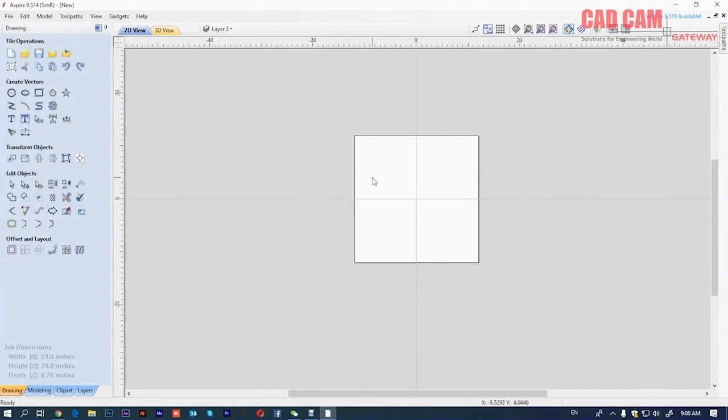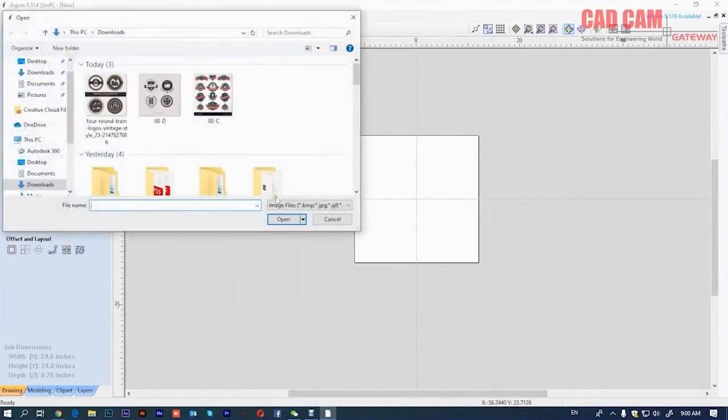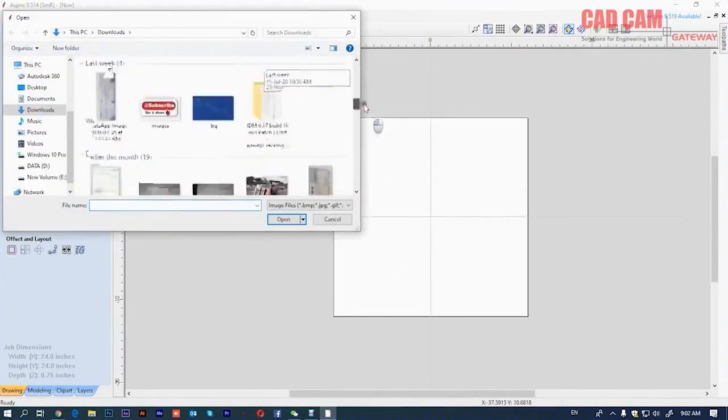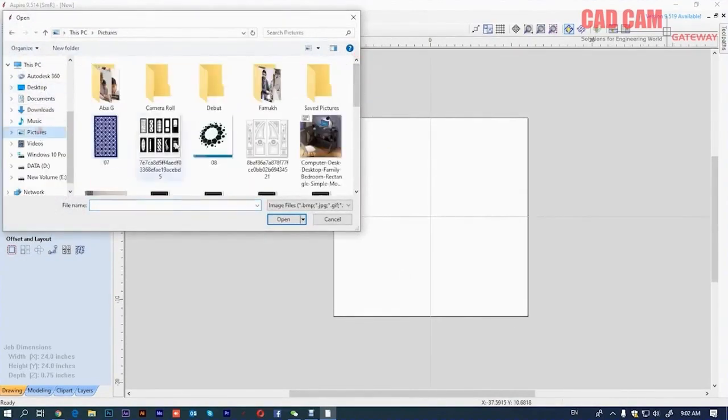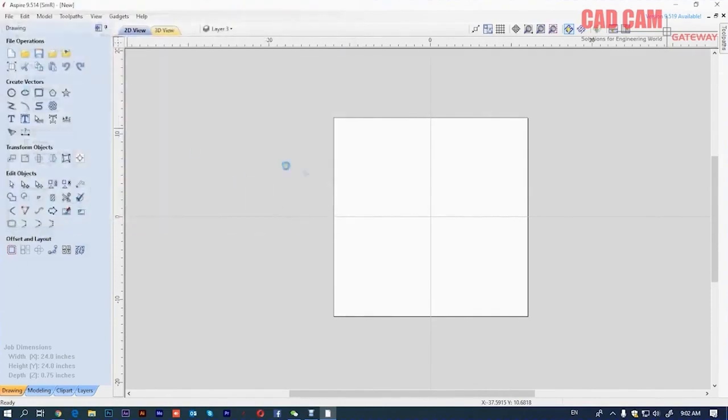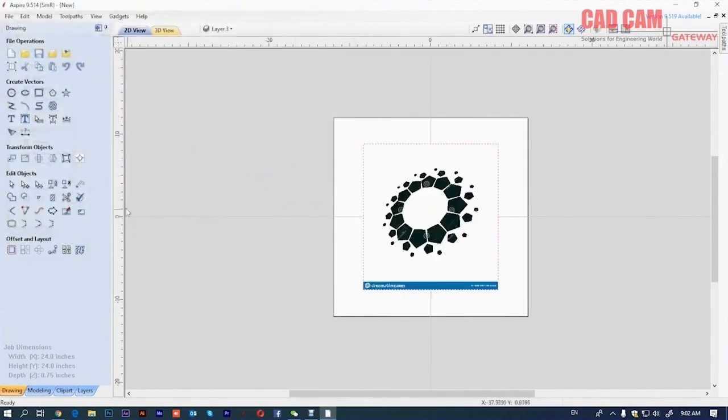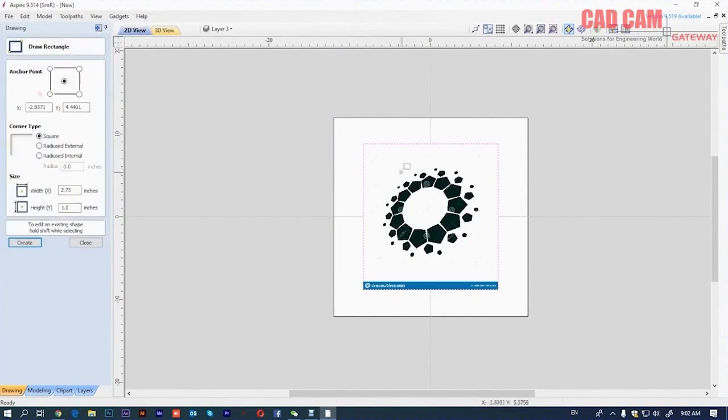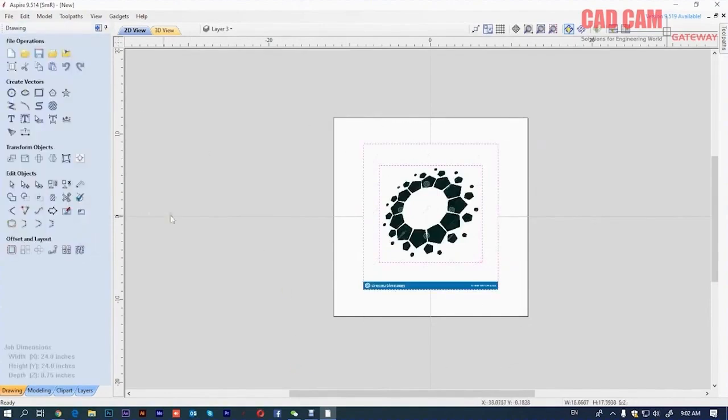Now we will create a monogram, so I'm importing an image for reference here. Viewers, this is a new command. First, I need to trim the extra area. I selected the object, selected both objects and used the trim command, and I've trimmed it. Move the image to the outside. Remove the rectangle.